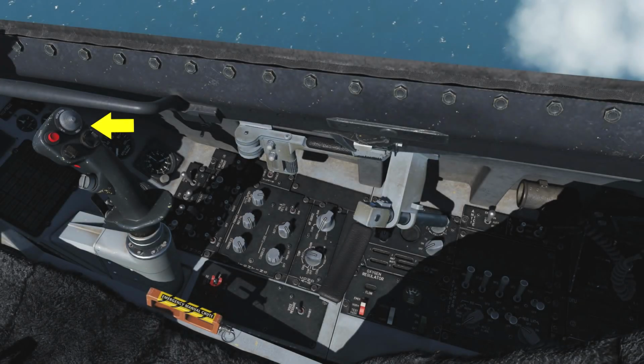The F-16 is quite unique for its time when it included a force sensing stick that uses transducers for both pitch and roll to determine flight inputs based on G and angle of attack. Despite being a force sensing stick, the stick still moves 1/8 of an inch in both axes, providing more natural feedback. Maximum pitch commands are generated with 25 pounds of force, and a maximum roll command is 17 pounds of force. However, in takeoff and landing, as well as aerial configuration, flick gains for maximum roll are reduced to 12 pounds.